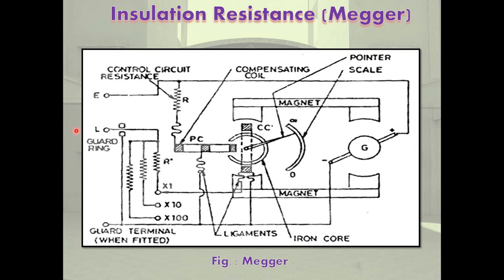When measuring the insulation resistance of a current carrying component part relative to ground, the following procedure can be employed. Two flexible well insulated conductors should be connected to the line and earth terminals of the Megger. The free ends of the conductors must have metal terminals with insulated handles. The probe marked grounded should be connected to the transformer tank, which must be grounded, and the other probe to a current carrying bar or lead connected to the winding under test.